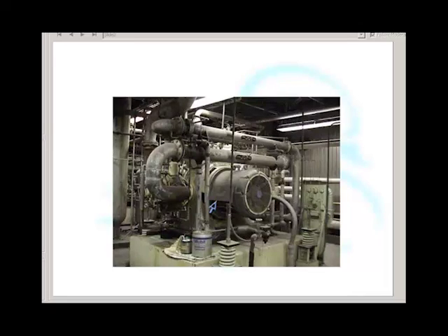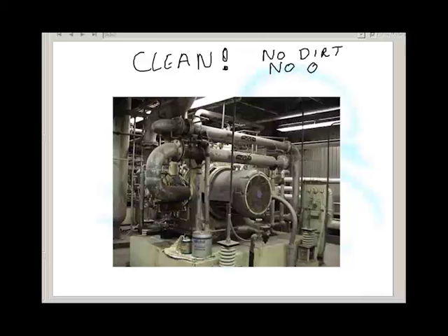This compressor has got to give us compressed air. Compressed air must be clean. Above all else, it must be clean, which means no dirt, no oil, and no water. Now, some of you may already work on sites where you are dealing with compressed air, and in a lot of places, it's absolutely terrible. It's full of dirt, it's full of oil, and it's full of water. If that's the case, you're going to have problems with your pneumatics.